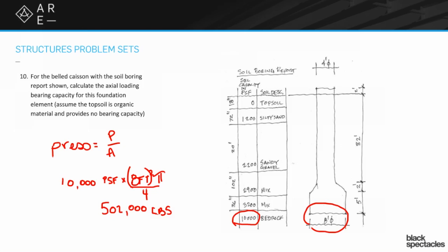Let's say there's a very detailed manufacturing place, like an iPhone manufacturing facility, where they're doing very specific and detailed manufacturing and they don't want a lot of vibration. Well, what kind of structural system would you suggest for that? You could think, well, wood? No, probably not wood. Steel? Well, steel is awesome, but it vibrates a lot. One of the great things about steel is it has a lot of ductility, but that may not be the right choice there. So maybe if it was something like that, it's probably concrete, some sort of concrete thing.